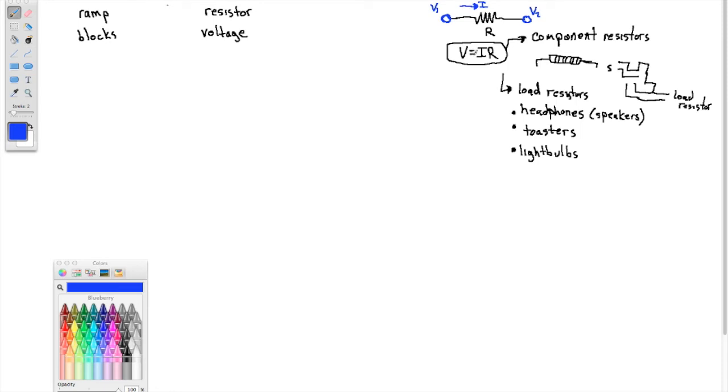And V here, this is Ohm's law. V is not the voltage at one end. It's the difference. It's always the difference that matters in electrical circuits. It's always the difference in voltage. Think about your gravitational potential energy problems. The first thing you did was set y equals 0 somewhere to solve these problems. And it didn't matter where you set y equals 0, because it was always the difference in heights that mattered. The same thing here. In fact, we can set V equals 0 anywhere in our circuit, and it's the difference that's going to matter.